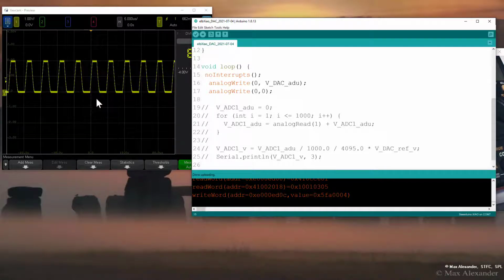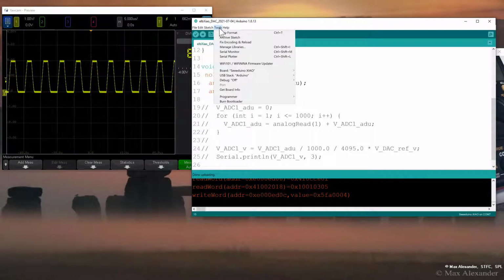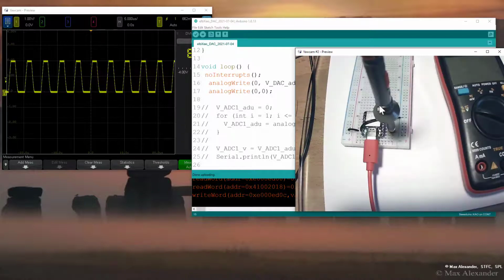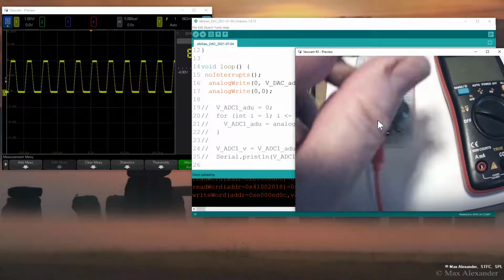It's looking great. The problem is that I disabled the port. I don't even see the module anymore. I can't upload code to it. I've bricked the module. And I can turn it off and on, and I can do whatever resetting I want to do, and there's nothing I'm going to do that's going to change what's going on the Xiao module. Unfortunately, this module is now bricked.